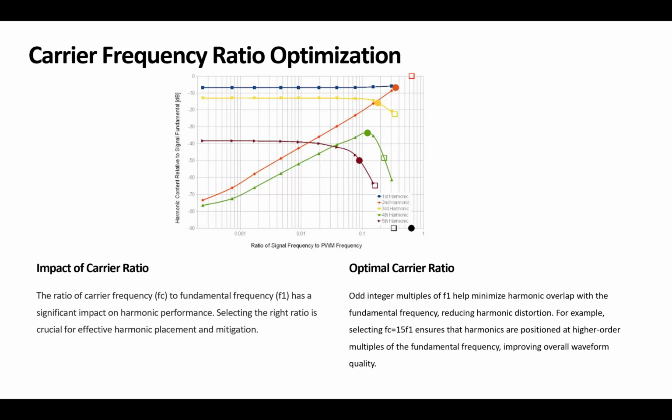using those technique, the PWM technique, already helped us to have lower amplitude of signals at higher frequency. So if the frequency goes higher and higher in the spectrum that we have, the harmonics that we have, when we go in higher frequency, we have lower amplitude. So it's already giving us a better situation than just a random switching. Okay, so PWM is already gifting us with those characteristics, but that's not enough. You still need to make a better situation.